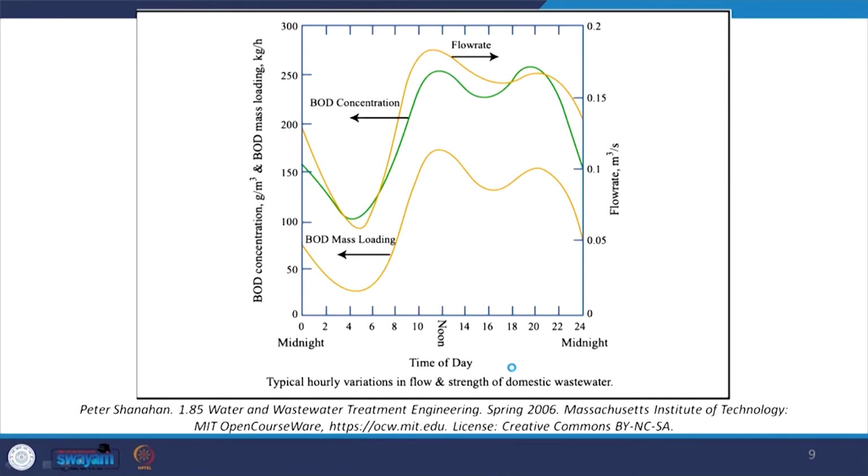So, this is the breakdown, for understanding what we are using the water for. And here I have another set of data, hourly variations in flow. For example, in the morning when I flush the toilet, the flow might not be a lot, but the concentration of the organic content is going to be high. But when I am bathing, the flow might be high, but the concentration of the organic content in that flow will be less. We need to understand that, because similar to people, bacteria too can't take shock loads.